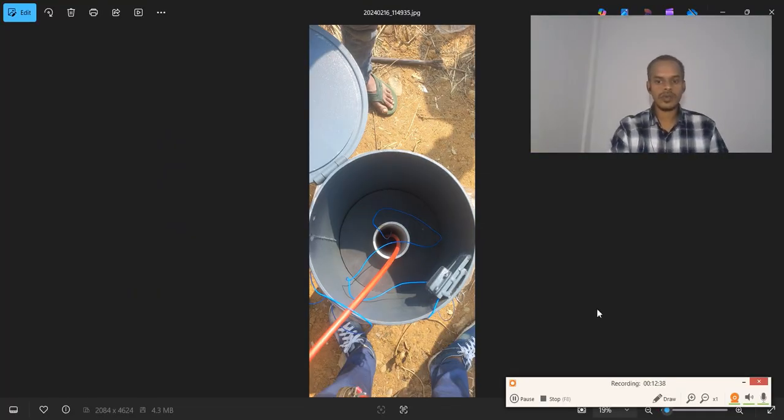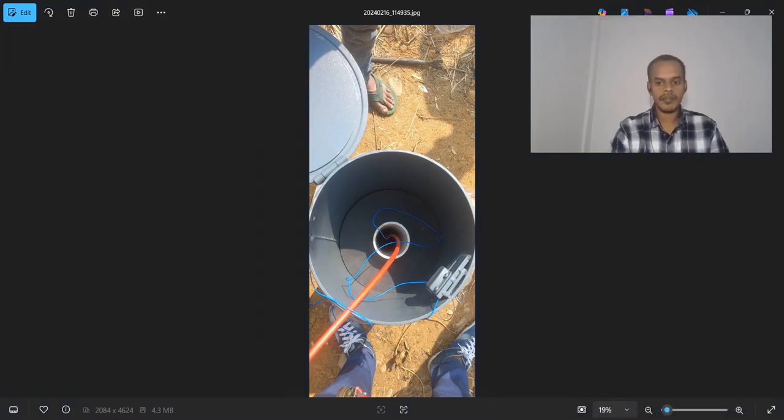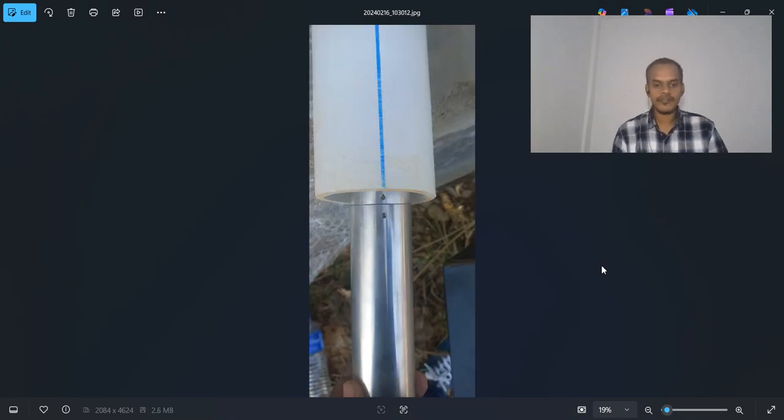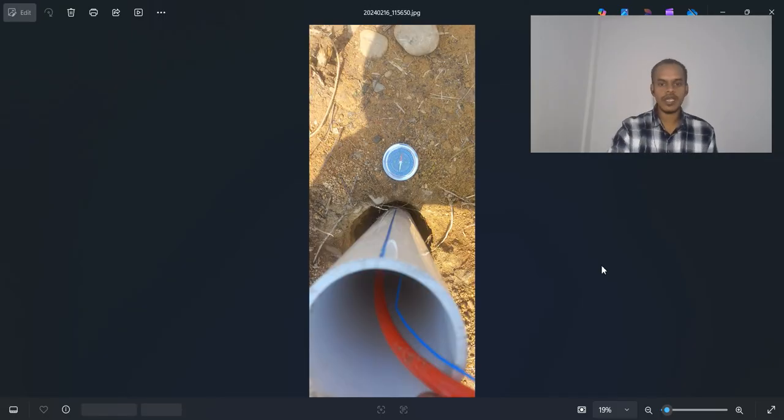So as you are seeing here, these stations, the sensors are generally fixed into some kind of an external covering, so that no other moisture enters into these. And once this is done, we will be burying the sensor into the ground, and we also face the direction of north. And also explain why we have to keep the sensor and the instrument, the digitizer, in the north all the time.